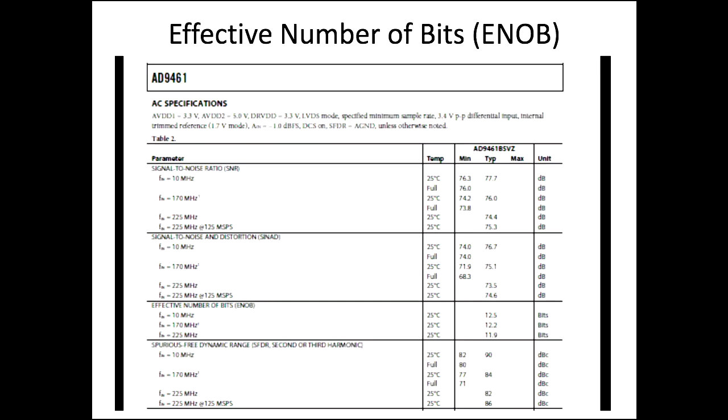So that's the reason you have to be careful when you buy an ADC. Sometimes you are increasing the complexity, but you are not going to get the return. Maybe a 12 bit might be enough. 12 bit might give an effective number of bits of 10. With 16, you are going to increase only 1 bit. You know what I meant?